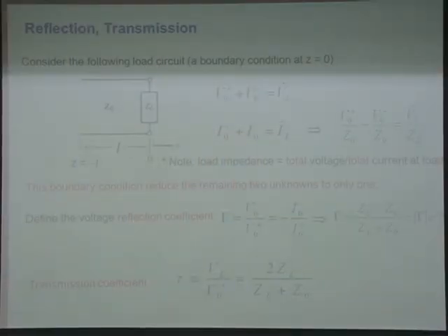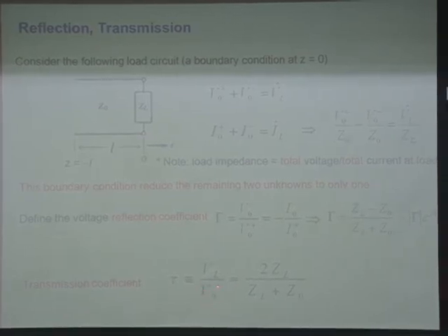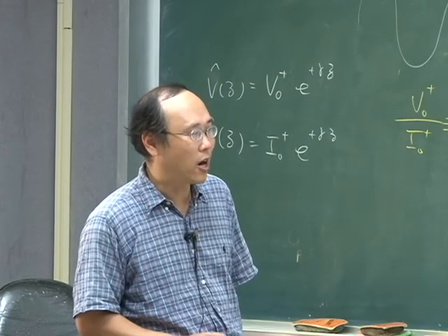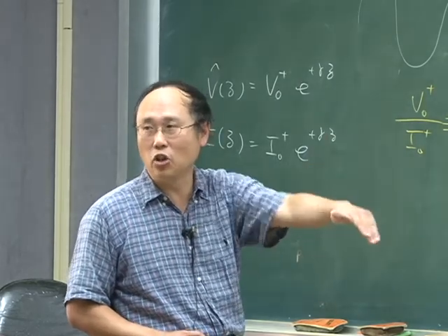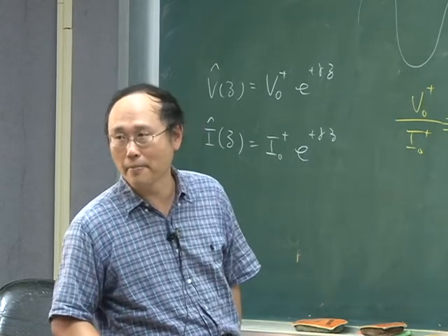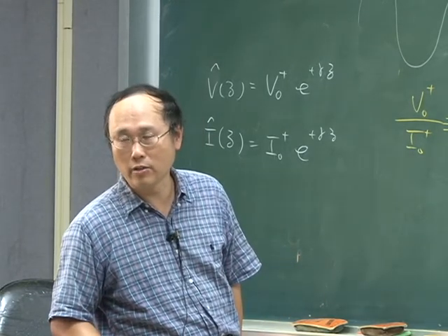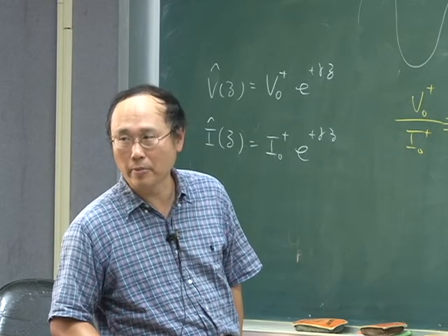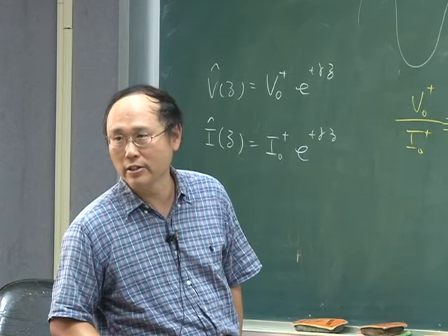Sometimes you are also interested in the signal transmitted into your load, and again, if you take the ratio of the load voltage over the full propagation signal, then you end up having an expression telling you the percentage of the voltage transmitted into your load, say an antenna. Okay, and then you can deduce the efficiency of your energy propagation, energy delivery.